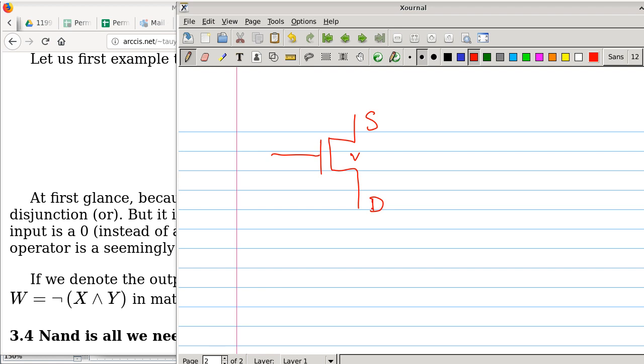So in the circuit diagram, we also kind of follow the convention. You can draw a picture any way you want because a schematic is nothing but a logical diagram of how things should connect. Because we naturally think of a lower voltage at a lower place visually and a higher voltage at a higher place. So in most circuit diagrams, VCC or the positive voltage is displayed on the top and then ground is displayed at the bottom.